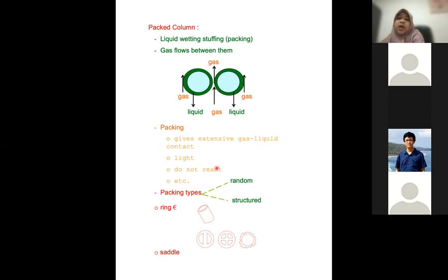For example, if the solute is corrosive, then we can't use a corrodible packing. There are also packing types, random and structured, and the random ones come in plastic, ceramic, or metal. Metal is of course easily corroded if you have CO2, sulfuric, or H2S gas, for example, or other corrosive gas.